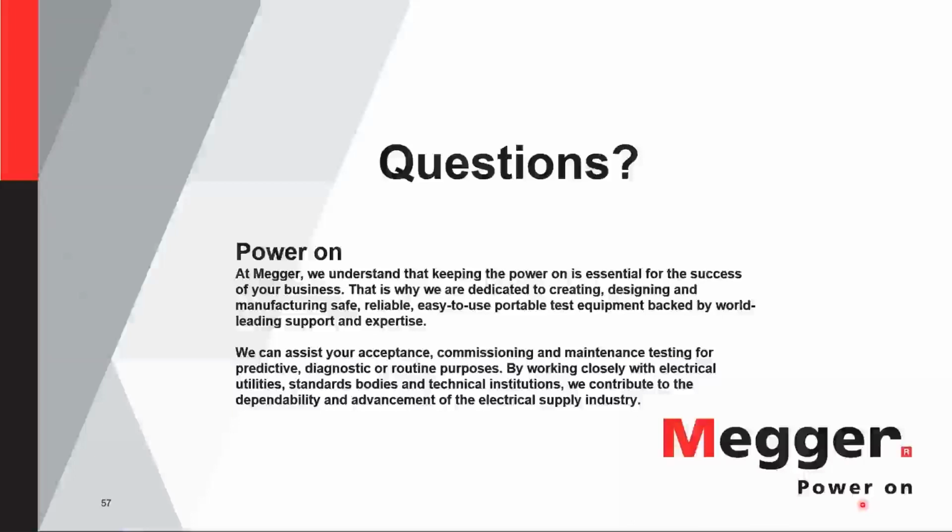Thank you, Daniel. Next question. Since the sample is usually taken from the bottom part of the tank, can we be sure the sample we are taking represents the actual condition of the oil? Well, the oil inside the transformer, inside the tank, is permanently moving. It's always recirculating due to natural effects or because it is forced. So it's never settled, and it's always going to be mixed.